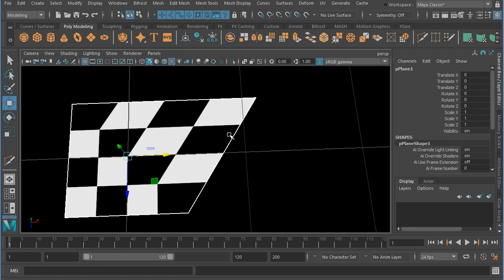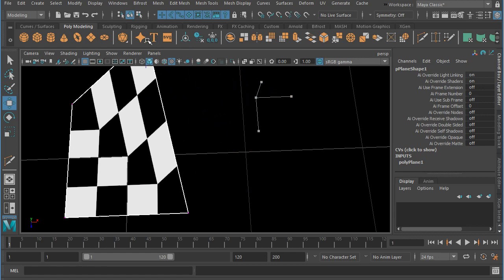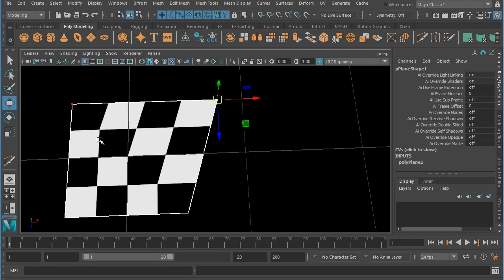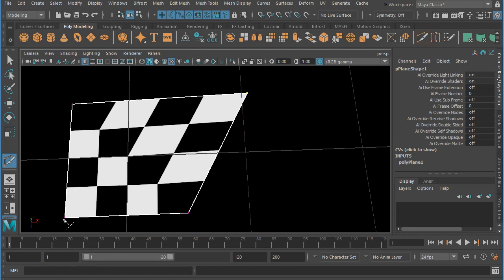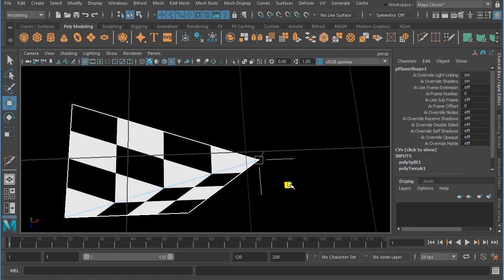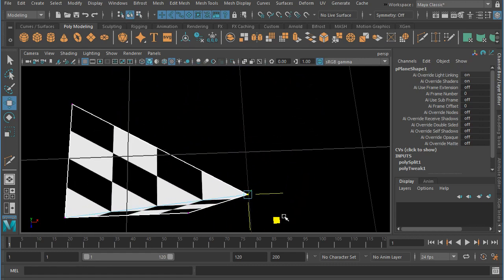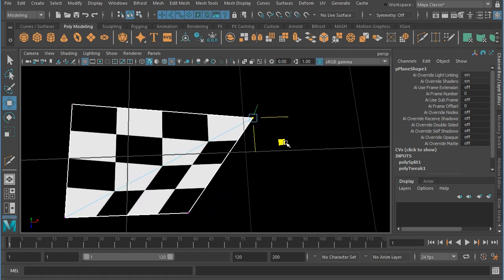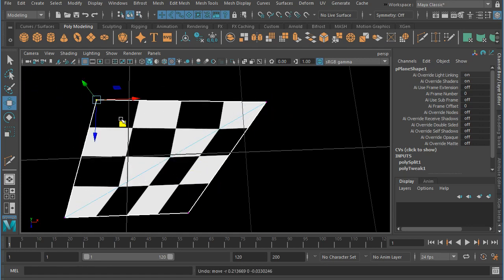It goes even worse than that in that you can start messing with these, and sometimes, it's probably not going to do it for me right now, but sometimes you may see this line kind of pop. What it will do is actually this. It's choosing arbitrarily where to split this into two triangles, because that's what the computer sees. The computer sees triangles. It doesn't see a quad quite so much. It's trying to place this in triangular spaces. So if I split this like this, both sides now are moving. Of course, they're getting distorted, but that's what it is. And yet, if I grab this side, once again, I'm stuck with that same problem.